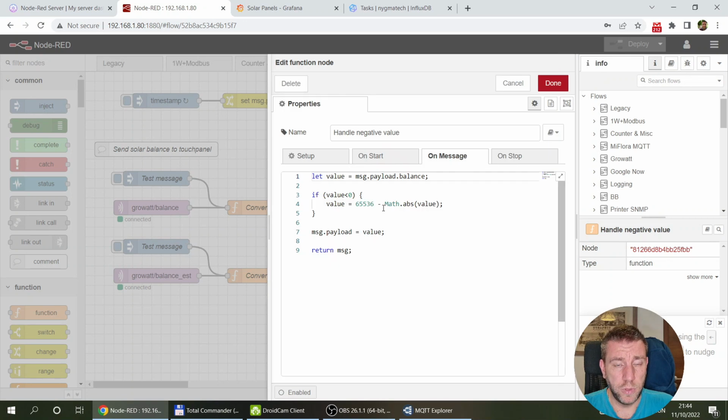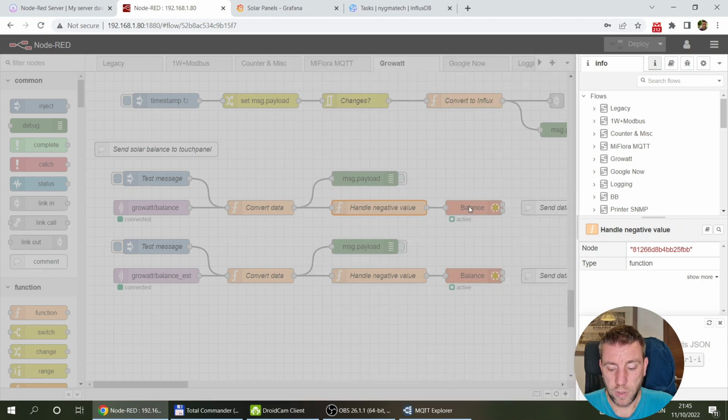And the Node-RED Modbus module does not really handle negative values. It just writes whatever value into the Modbus register. So I take care of it, because at least my PLC treats negative values with the first, or the highest, bit turned to 1. So this is how you calculate the negative value, basically. So I need to do that conversion, and I send it off to my PLC.